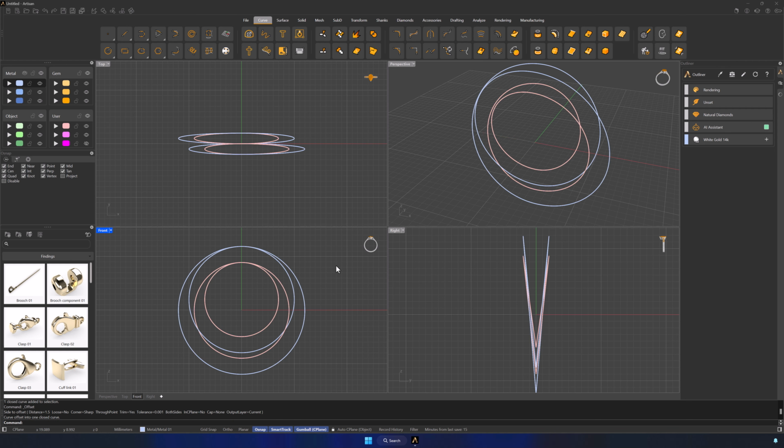click to create it. As we can see when selecting the curves, the offset curve is created with many control points. This makes it difficult to work with, as it creates poly surfaces instead of a clean surface, which results in too many control points. To improve this, select both curves, go to the Curve tab, and click on the Fit command.